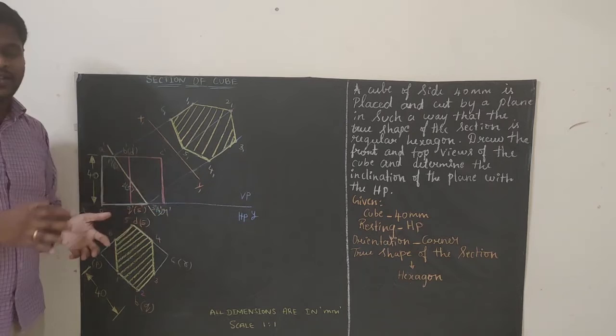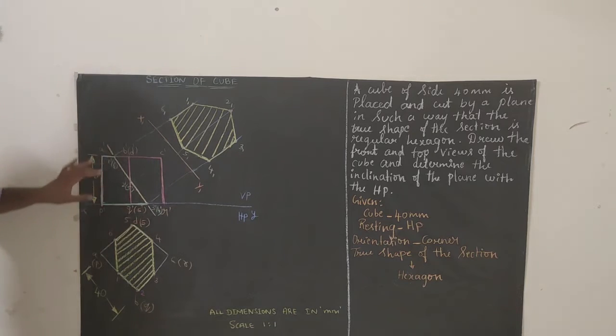These blue color lines should be drawn with your 2H pencil, and you have to darken here. Okay, this is the part which we are having. Draw this diagram with a 2H pencil, and from this portion you have to mark. Just use your HB pencil and draw the cutting plane, and just darken whatever I showed in your green color chalk.